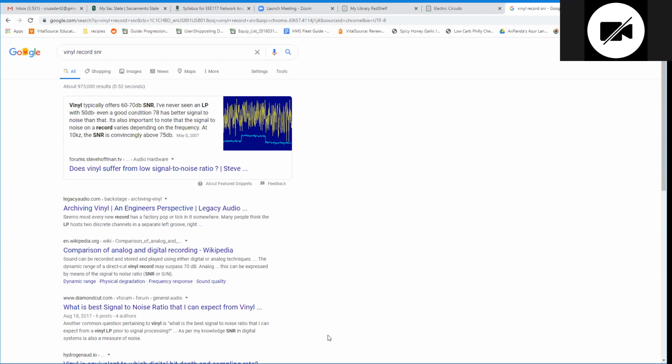You can do that. There's SNR meters. You get a speaker that will output a specific tone, and the SNR meter will read that tone, and then it's going to record what comes out of the speaker from the vinyl record, and compare it, and give you an SNR measurement. That's literally what dB meters are used for, right? In an experimental environment, of course. You don't have the dog in the background yapping about it, okay?